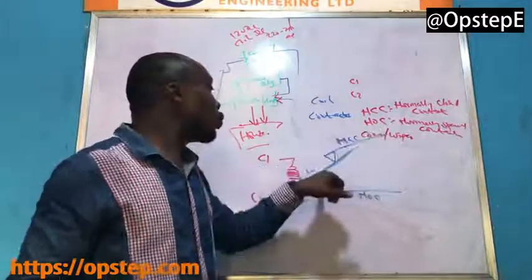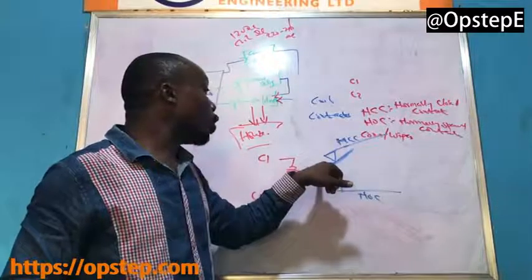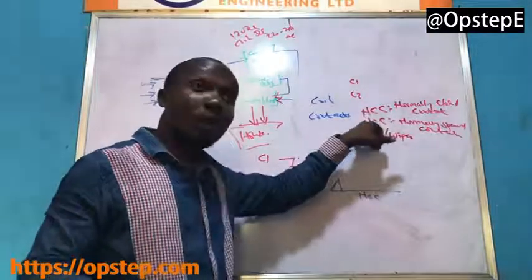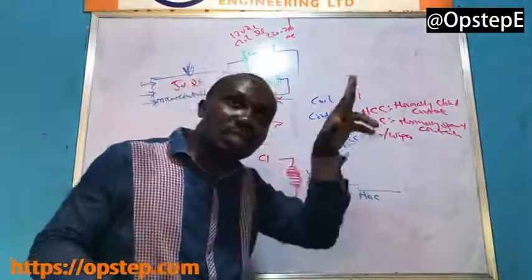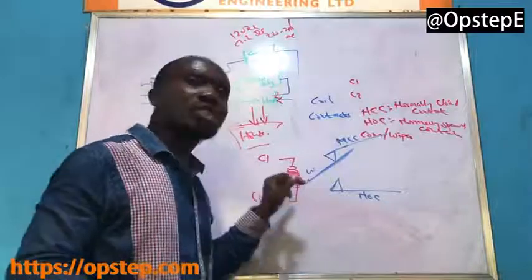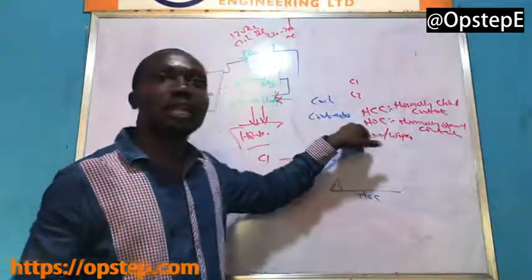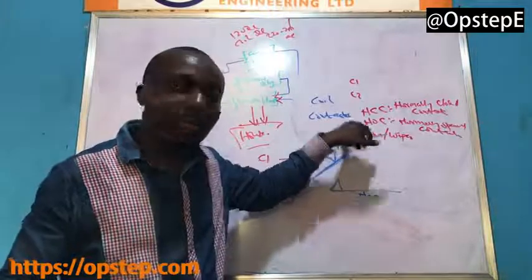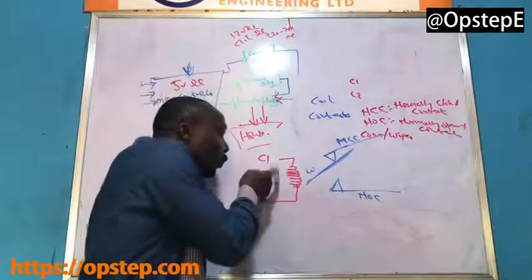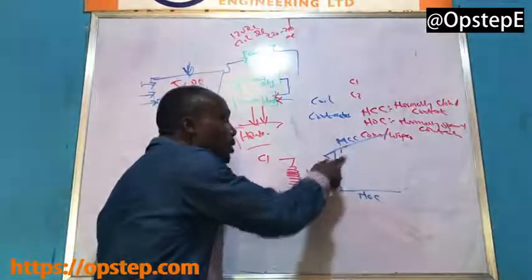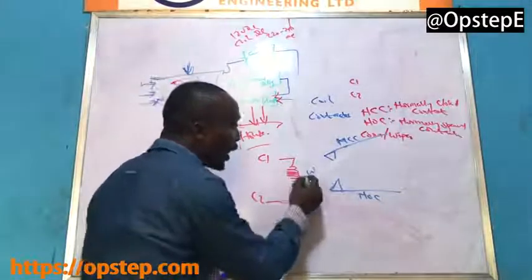Which means if you get a continuity buzzer and you put it on the wiper and the normally closed contact, the one that buzzes when the coil of the relay is not energized lets you know that is the wiper to its normally closed contact. Now the moment you put voltage on this coil, this wiper switches from this place and latches itself in.